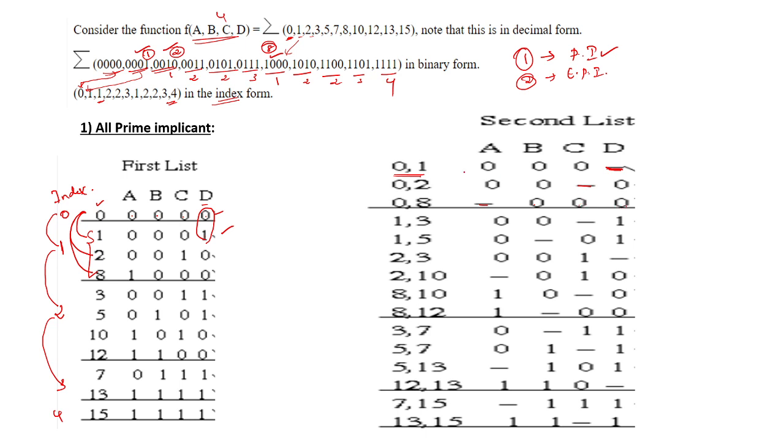and the remaining values as such. Next we check 1 with 3, 1 with 5, 1 with 10, and 1 with 12. If there is a possibility of a 1 bit change between those min terms, we represent it, or else we can leave it.